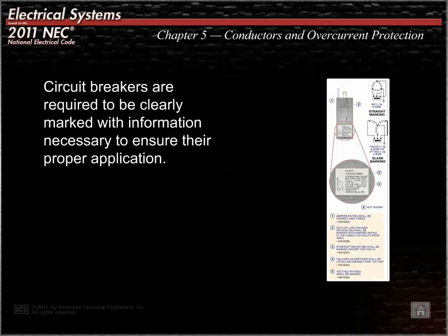Circuit breakers shall be marked to indicate the ampere rating, the interrupting rating, and the voltage rating of the device. Additionally, circuit breakers which are permitted to be used as switches shall be marked to indicate such use.